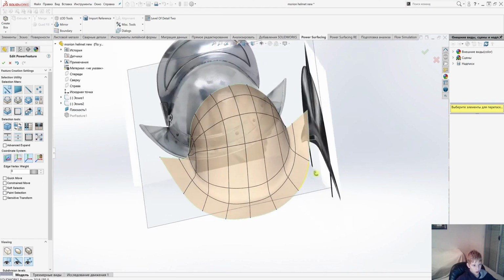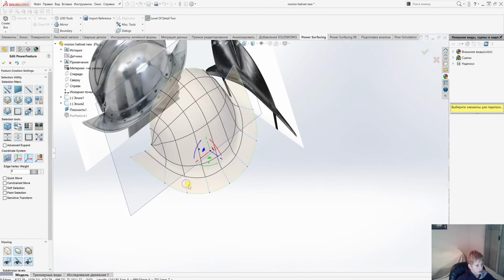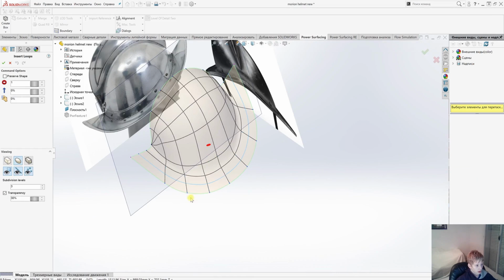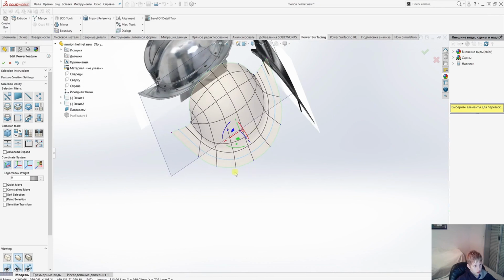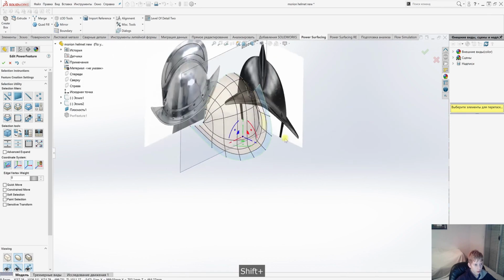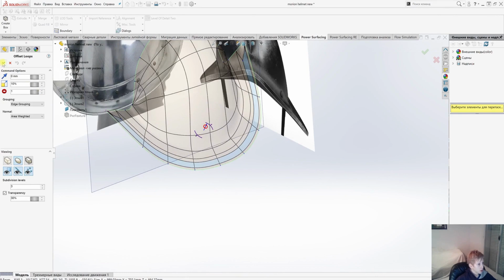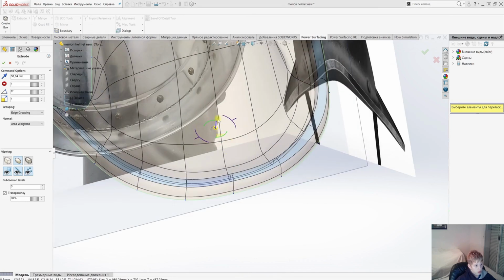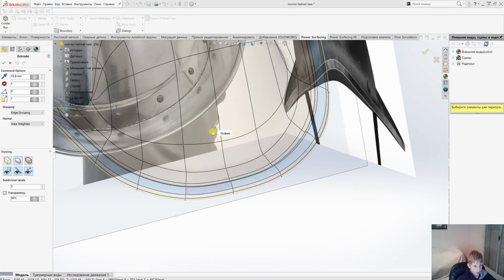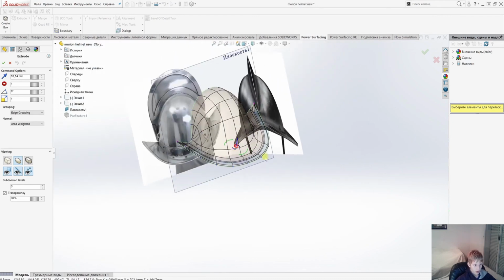Now let's create a small bulge on the edge of the helmet. We'll create a slight subdivision of the geometry between the first and second perimeters. Okay, now let's select all our polygons. Right click and choose Insert. This command is analogous to the one in 3ds Max. Then right click, choose Extrude, and extrude just a little bit. What we're doing now is creating this bulge on the edge of the helmet.